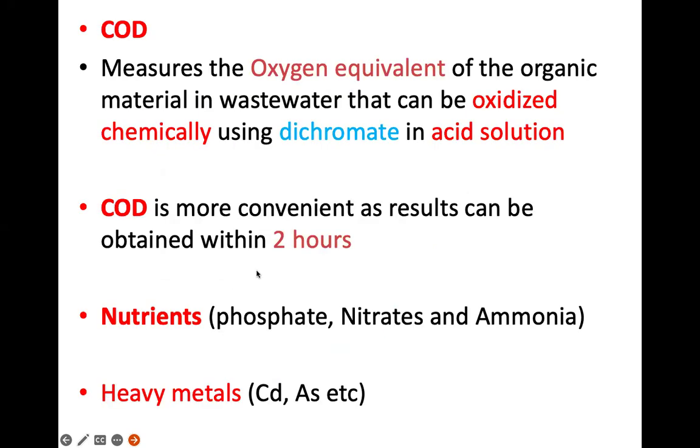Now, the chemical equivalent of the BOD is COD. Normally, BOD can be computed after 5 days. Why? This is because you need to compute the BOD of the first day, then keep your sample in an incubator for 5 days, maintained at a temperature of 20 degrees, and then you compute the BOD after the 5 days and you find a difference.